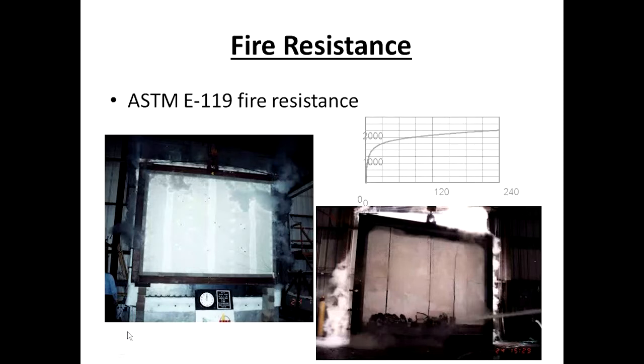So let's think a moment. If this is an office wall, and I have my desk right next to this office wall, and I have a garbage can full of paper that I've made mistakes on and thrown into the garbage can. I have a fire raging on the other side of that wall where the temperatures exceed 2,000 degrees. Is the temperature on my side of the wall at such a level that the waste paper in that garbage can will start on fire? If it does, you don't need the wall because you just breached it. And that will happen at 451. So the point of the test is to keep the temperature below that point of pyrolysis of combustible materials.